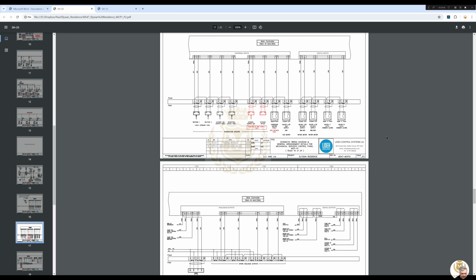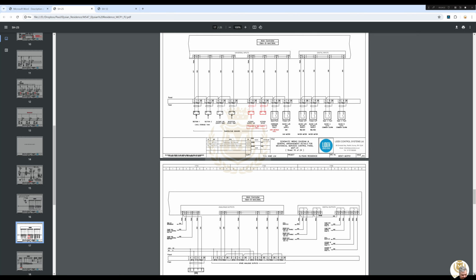So I think we need block A UPS common alarm moving across to UI 16 and block A and B gas supply putting in its place, swapping them two across. So I've got to do a request for information there now, why they think a UI 16 is going to be fast enough for a pulse, which is not. It's nonsense. So I've got to inform them of that.